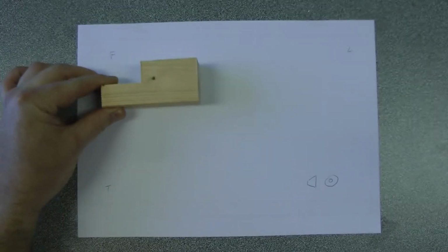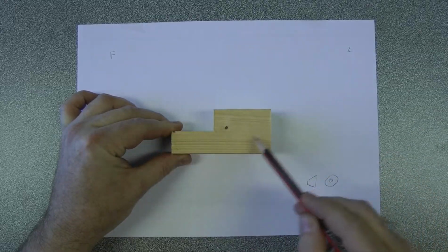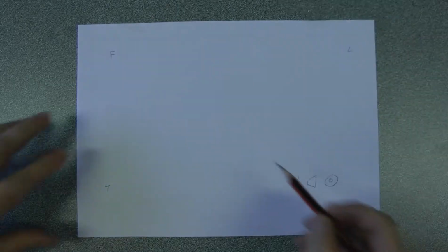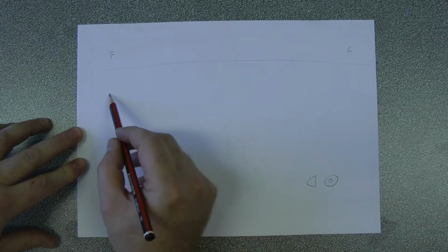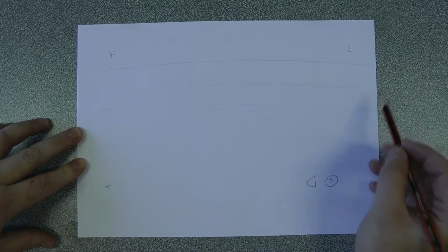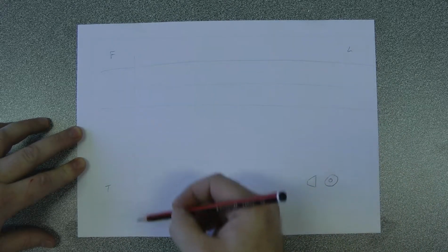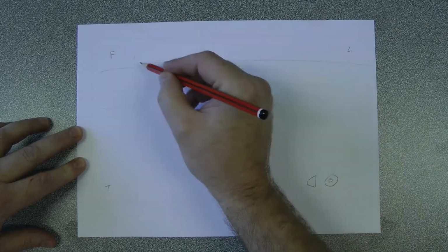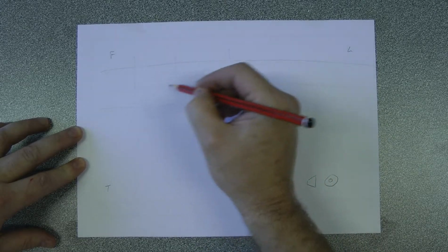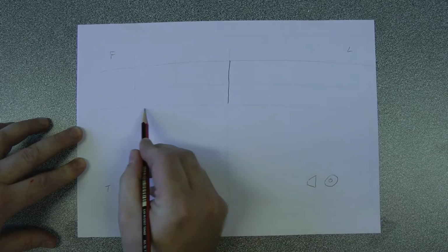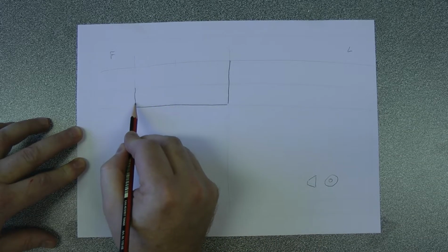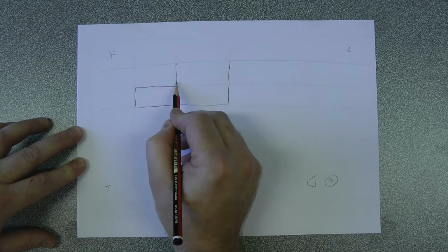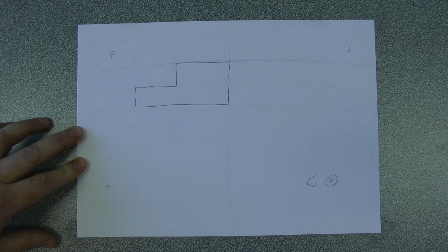So to start with, I'm just going to do a rough sketch of what this is going to look like, and I'm going to say, well, my front view, I know it's basically a rectangular block with another rectangle cut out of it. So I'm going to do that by laying out some construction lines. Those are my horizontal ones. I'm going to have some coming down, and then I'm going to do my darker lines. So this is my basic rectangular shape. This is the bit that's been cut out. So I'm going to come down, my front view is going to look something like that.